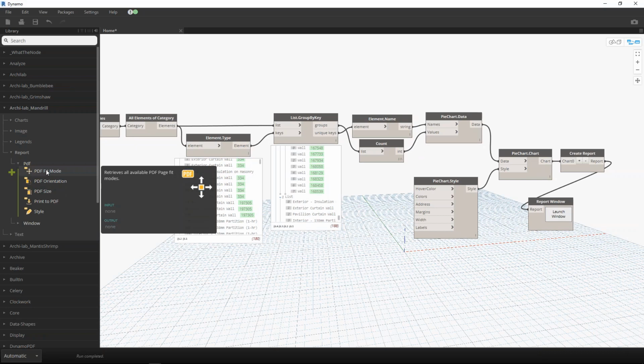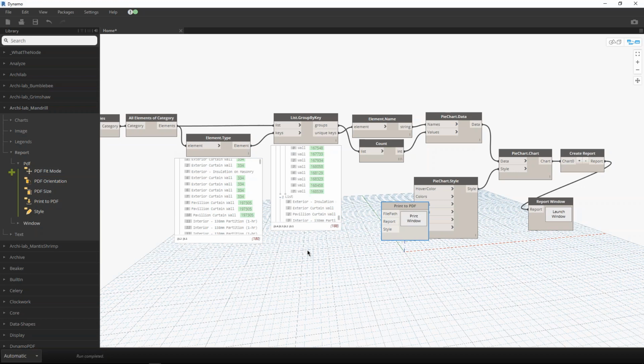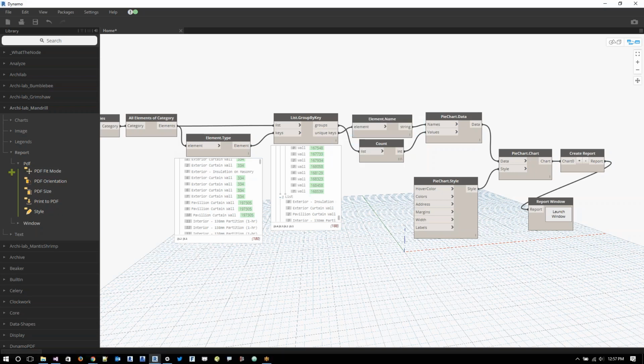We want a stopgap between making stuff in Revit, where the furniture schedule, the wall schedule, whatever, is constantly changing. Then we use Dynamo, export that to Excel, hit refresh in Power BI, and it gives us the same output as Mandrill, but we can share that on the web throughout the company, and it's just really fantastic.